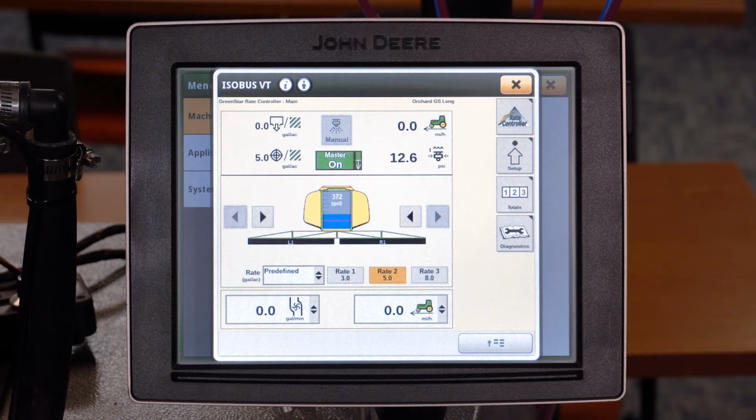If the pump is running, the first thing to check is the inlet. Is the valve from the tank open? It happens. Next thing to check is the strainer. Is the strainer clean and clear?